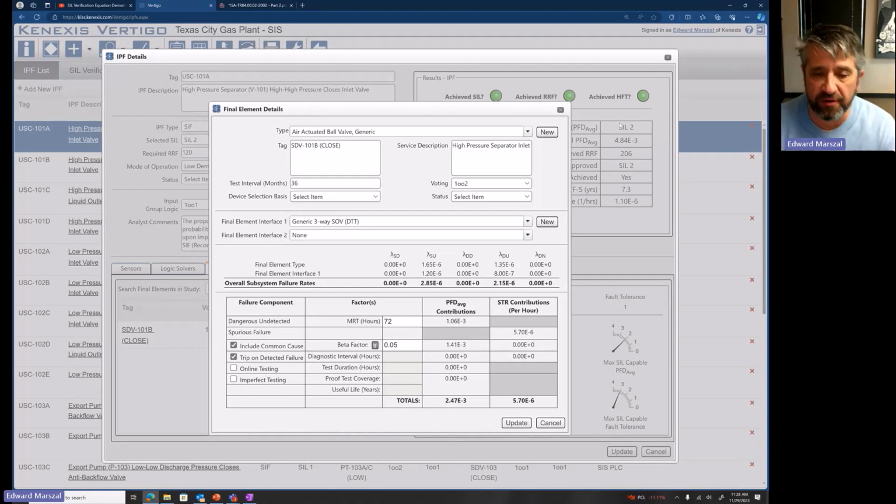For a 2 out of 3 voting arrangement, when you detect that the first component has failed, you can program the device to change the voting arrangement to either now be a 1 out of 2 or a 2 out of 2. So a bad PV, you could throw out the bad component and now revert to a 2 out of 2 vote or a 1 out of 2 vote.